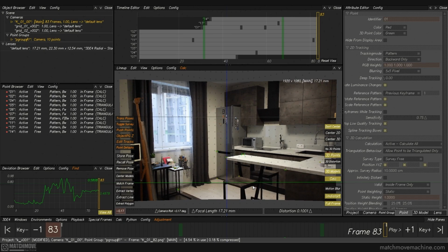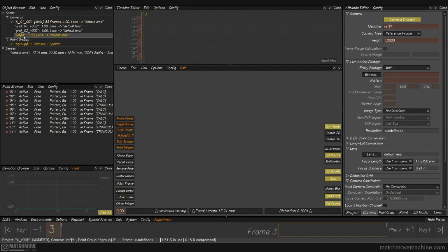So how do we determine the depth? We either need the real coordinates of the points or additional angles of the same location. In other words, regular reference photos. And let's go through the second method, working with reference photos. We add a new reference camera and load into it a photo taken in the same location but from a different angle.